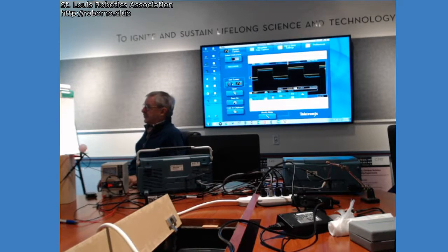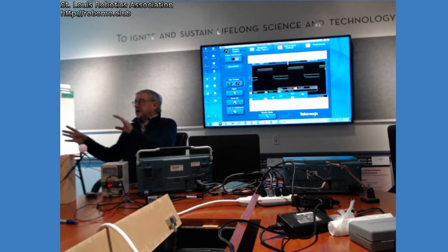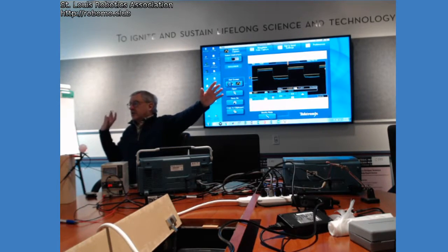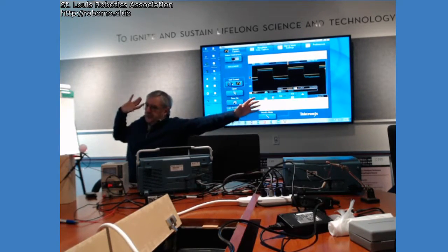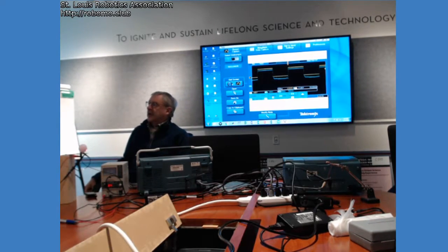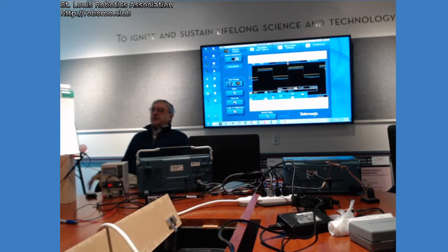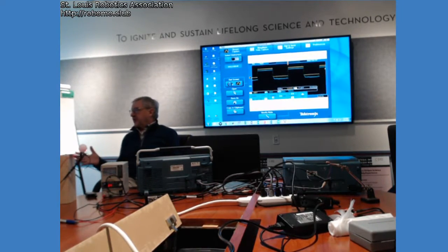That kind of thing is like, let's say we wanted to run at 10 megabit per second in outer space with satellites hundreds of miles apart from one another. We would be doing all kinds of fancy stuff with amplifiers. Because what you're doing with that amplifier is you're making that photodiode into a phototransistor. You're just doing it externally. The transistor of the phototransistor is an amplifier.